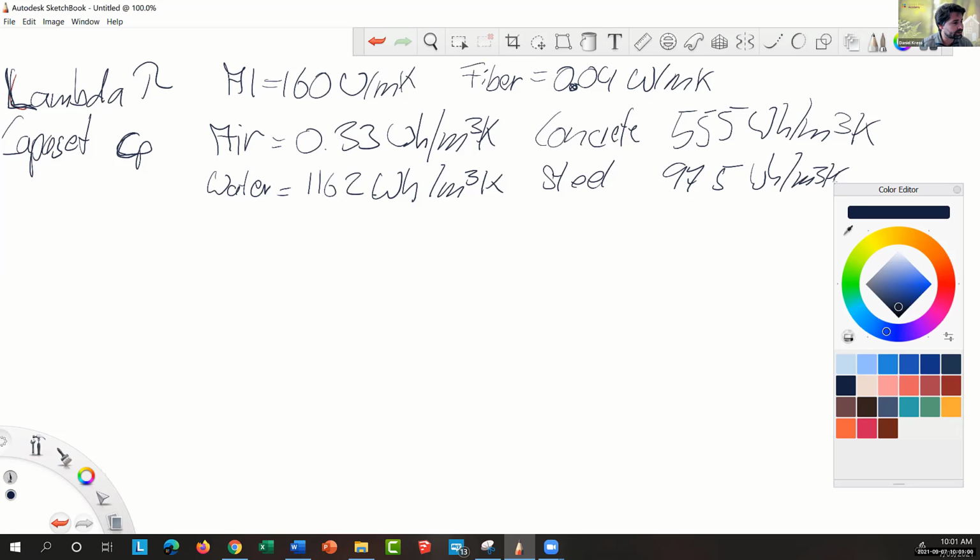And now you see that massive difference in the capacity of these two materials. This is the reason why water creates a really quick overreaction and overcorrection of the temperatures indoors, because we are at more than 3,000 times the capacity for the same volume. That's the reason we have to be really careful with water-based systems in a passive house.